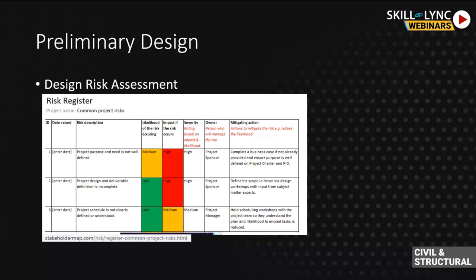You try to do whatever work you can do on the ground and then lift it up. If you have cladding, put the cladding first and then lift the structure, rather than putting the structure first and then putting the cladding on it. This is the way we mitigate the risk. And this should be highlighted on your drawing, so that whenever it reaches the site, it gives the site engineer the idea of how it should be built.